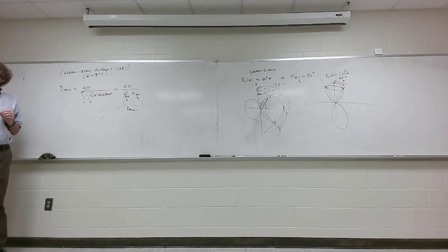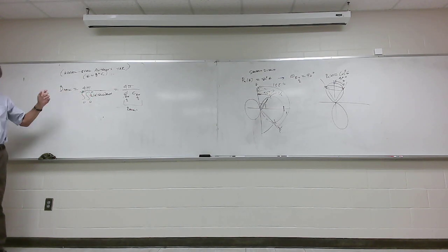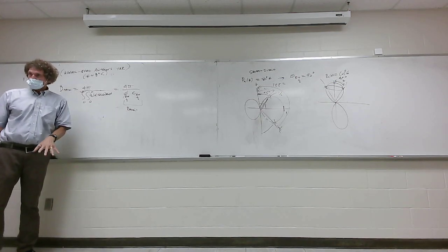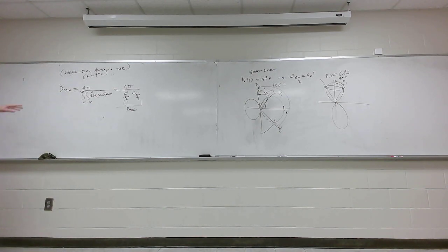Now that's a cheap, very easy and effective way for a guy to do some measurements in an antenna chamber and not have to measure the whole pattern everywhere to do this calculation. He just finds the half power beam widths of the main beam in theta and phi, and he's got that. But these things are in radians and they're very small numbers. Got that? So these are high gain antennas, things with high D max. All right? I want to just throw that out there.